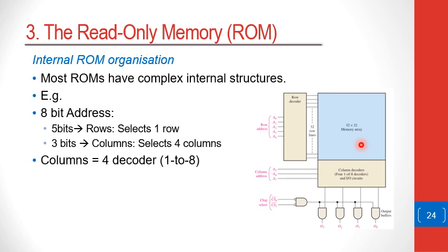So on top of having a 32 by 32 array memory, there is a combination of 4 decoders which have to be selected. These are 4 1 to 8 line decoders, as well as a row select. And this is much more complex than a typical structure of any other type of memory for a given simple 256 by 4 memory size.